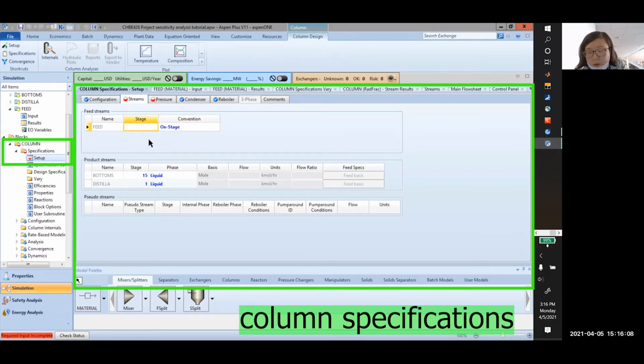We're going to have, let's say, because we have 15 stages, let's pretend we're starting at like stage 8, because that sounds around right. Number 1 should be your distillate first stage, so it's counting top to down. 15 should be your bottom stage, and you'll have both of them in liquid phase. Remember, they're not vapor, they're liquid.